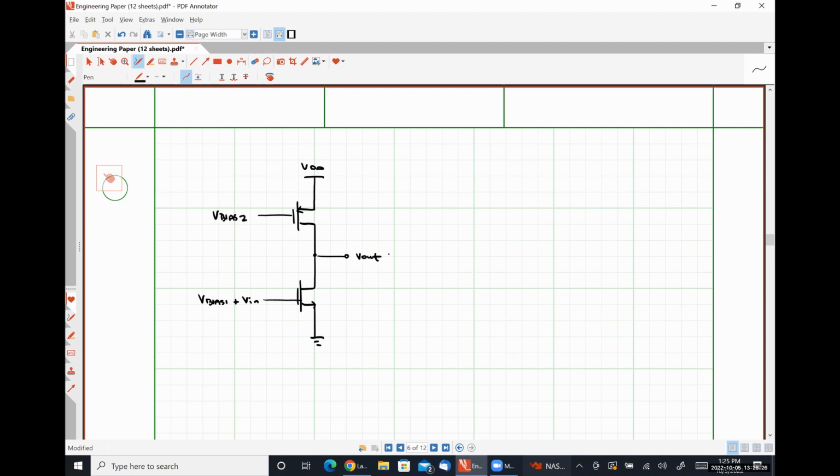And then here is where we would measure our output voltage. So effectively, the biasing portion of our previous network, which is really just the signal chain of VDD R1 in series with R2, is taken care of by just applying a DC voltage. And then we superimpose our AC signal on top of that. The role of the resistor RD is now being played by this PMOS transistor, okay?